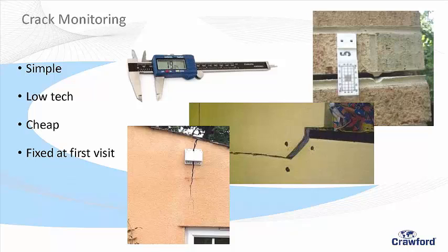Non-intrusive in some sense, in that we're not knocking on the policyholder every 2 months to take a reading. These are giving us readings every day, remotely. Very low tech, but it's telling me degree and direction of movement. Because I may have proved it's a tree by the roots and the clay, and I've told them it's not the drain, but if they say, but is it moving, I need to show it's moving. So this is the package of evidence we might need.